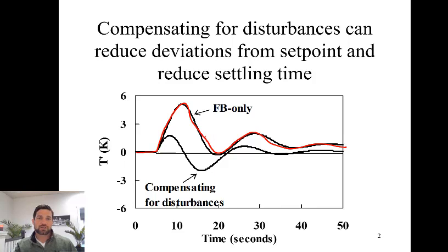Again, if we just look at this general control for this feedback control only process, one of the things we might notice is that the oscillations don't occur around the set point. So we could do a better job tuning this controller. My question for you is, how would we retune this controller in order to achieve a better process? Why don't you pause and think about that for a second, and then I'll discuss.